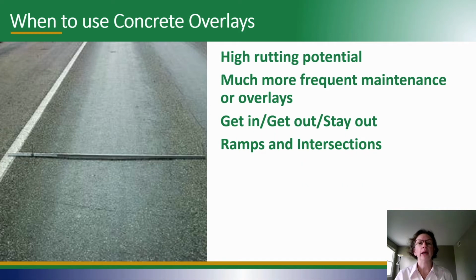Let's talk about when concrete overlays are particularly useful. Concrete overlays can be used in areas with high rutting potential, where much more frequent maintenance or more frequent overlays are required. With a concrete overlay, you can get in, get out, and stay out for much longer periods of time. Concrete overlays are used on ramps and at intersections.